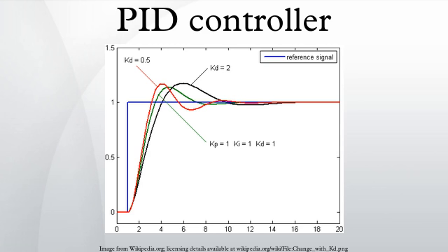In contrast, a small gain results in a small output response to a large input error, and a less responsive or less sensitive controller. If the proportional gain is too low, the control action may be too small when responding to system disturbances. Tuning theory and industrial practice indicate that the proportional term should contribute the bulk of the output change.